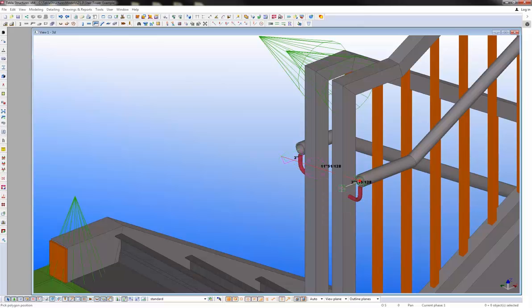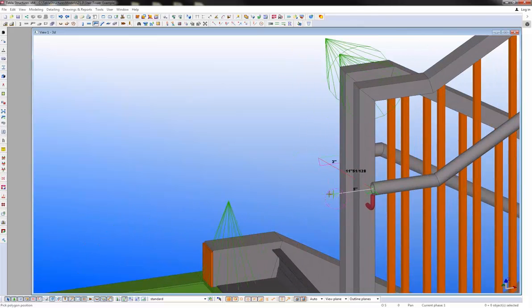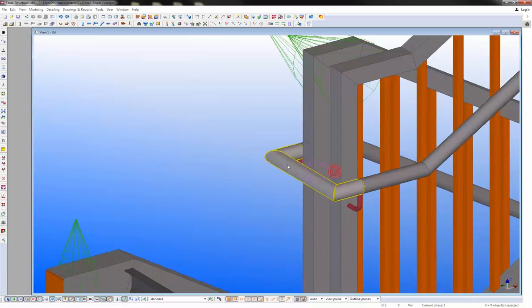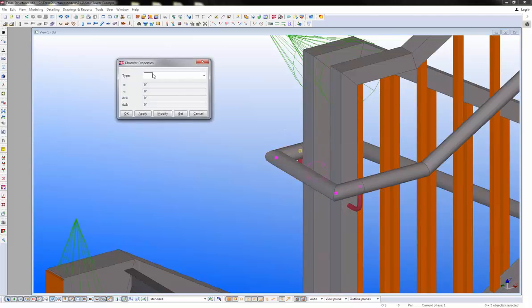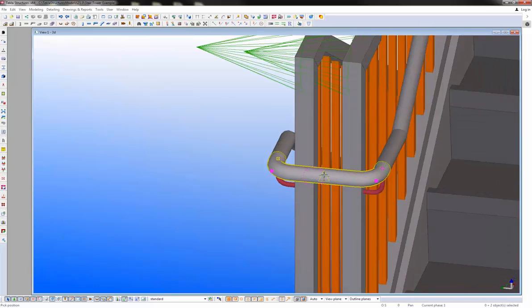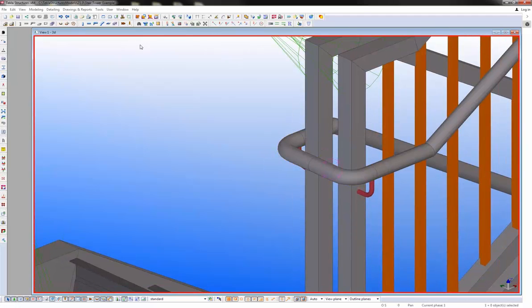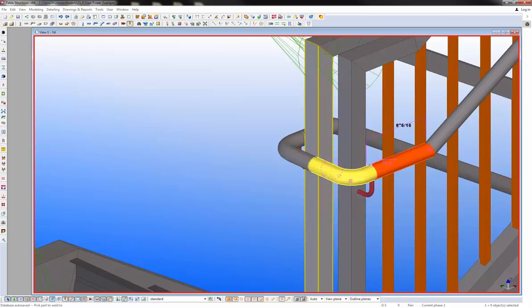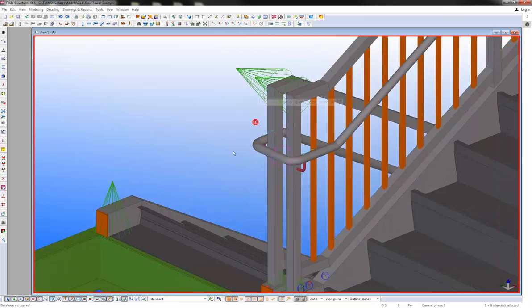Come out 3 inches. And obviously you can make these dimensions whatever you like. So I'll come back 3 inches again. If I'd like, I can put a radius on here. You can do any type of finish you'd like on there. And then if you want, you can go ahead and split that so that one section will be shipped with the upper rail and one section will be shipped with the lower rail. Make sure those are welded in place. You always have to remember that Tekla is very shop fabrication and erection driven, so you want to make sure you add welds where welds are required.